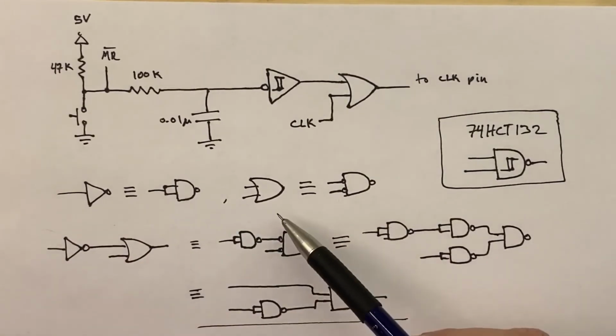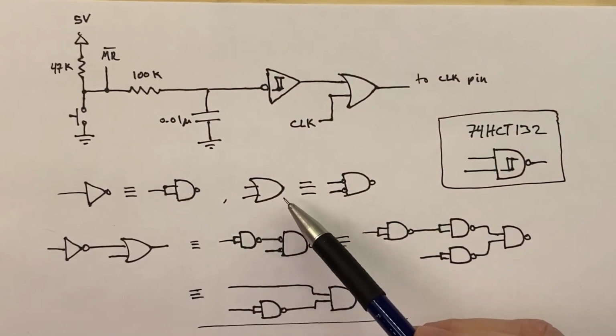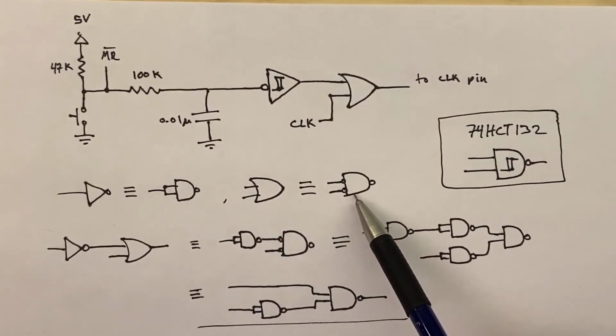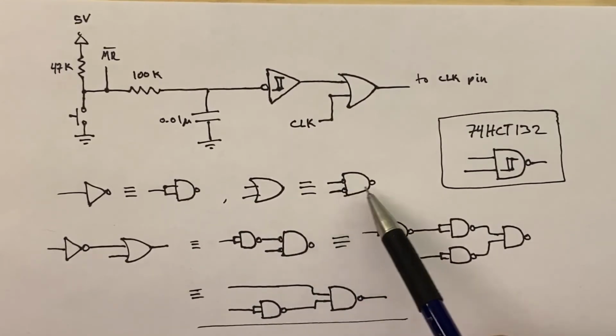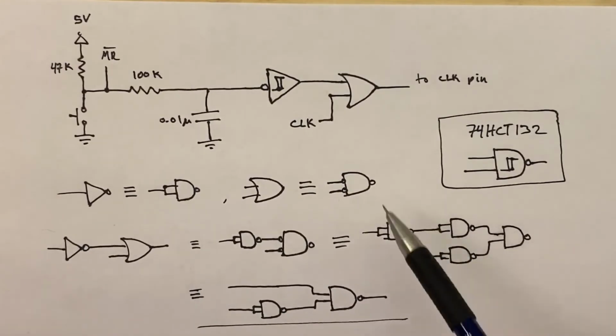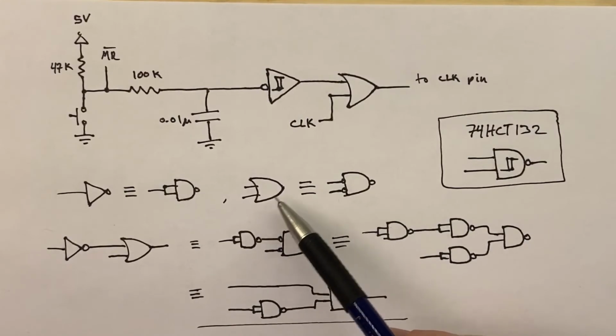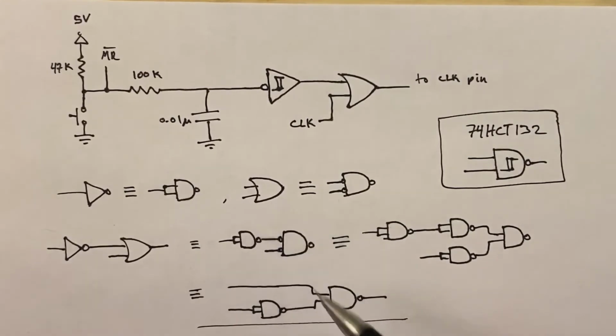And also there's this cool little identity where if you have an OR gate, it can become an AND gate, and all you have to do is negate the inputs and the outputs. And it also works vice versa. An AND gate can become an OR gate by just negating both the inputs and outputs, kind of like De Morgan's theorem is what it's called.